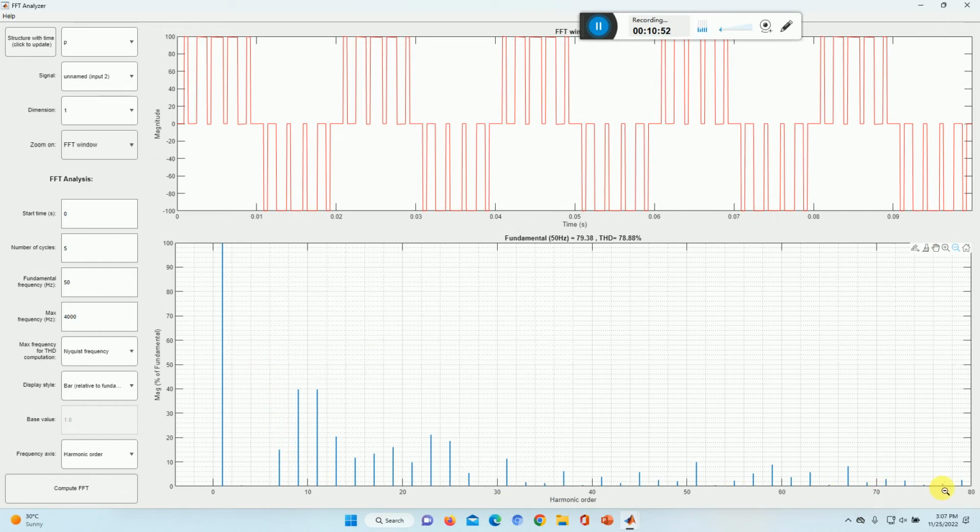Let me brush over the harmonics. These are the ones in red color. Right, these are the harmonics. We have taken the modulating frequency as 5, and 5 into 2 is 10, and 10 minus 1 is 9. So the 9th is a harmonic, then the 7th is a harmonic. That is the way. And what is not there is the 3rd and 5th.